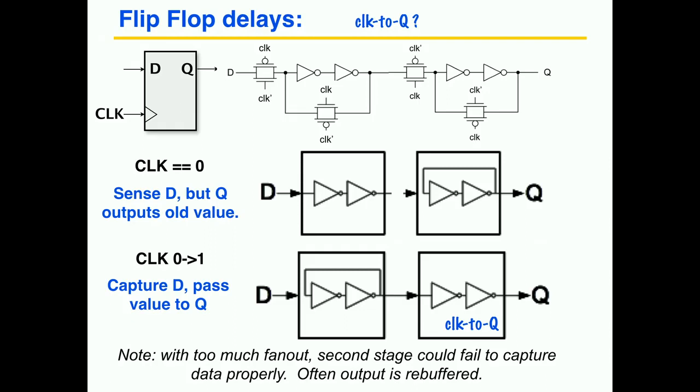The setup time is the time that it takes, when the clock is low, for the signal to get through these inverters, ready to the point so that when the feedback loop is closed, the signal comes back around and reinforces itself. So the signal has to come early enough before the rising edge of the clock to make it through both those inverters, and that's what defines the setup time. Typically for this type of latch, or flip-flop, if you forget about the fan-out here, the setup time and the clock-to-Q time should be comparable, similar to one another.